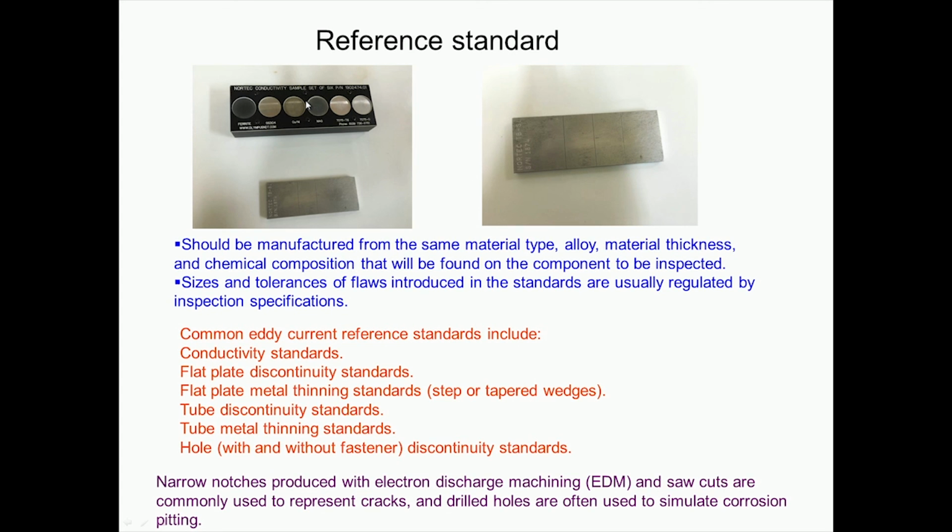This is a conductivity reference standard, because you have seen conductivity is one of the important parameters which controls the depth of penetration of the eddy currents. So, in certain cases you need to calibrate the instrument with regard to the conductivity as well.